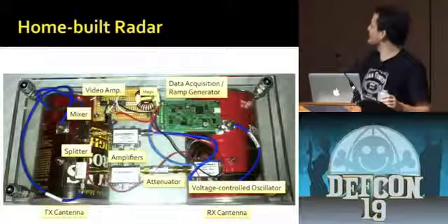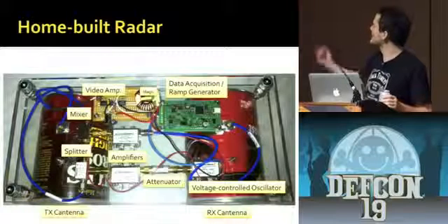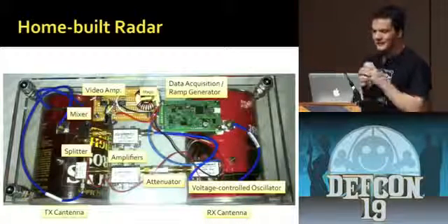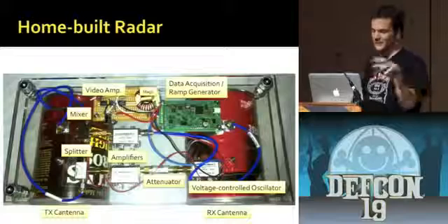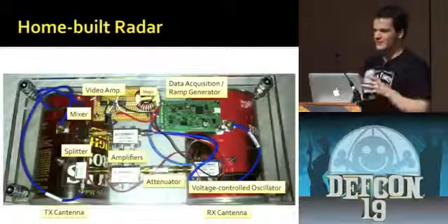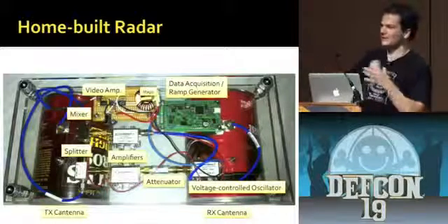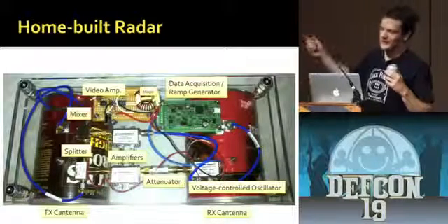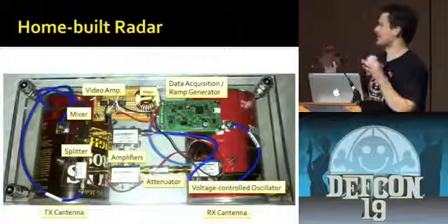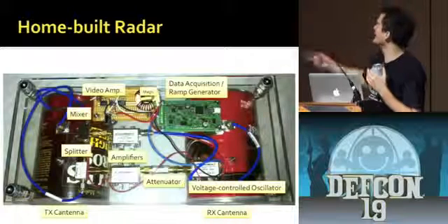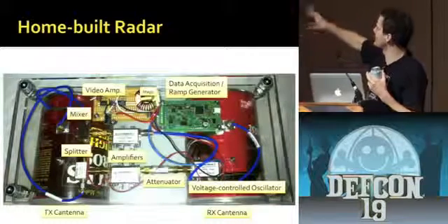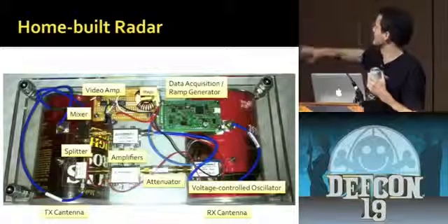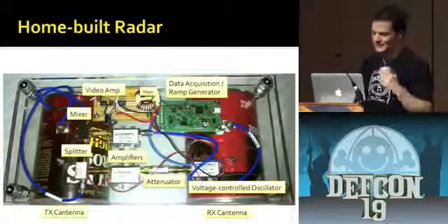The reason that's there is because I was trying to make this thing USB powered, so I just wired it onto the power for this other stuff. Everything on here runs off of 5 volts. So I plugged the USB in, and the computer doesn't like that. It just turns off the port. The problem was the inrush current was too high, and I needed something to slow that down. So I figured I'd put an inductor in there. The only one I could find was this big choke transformer thing, so I just shoved that in there, and that worked. That's all that's for.